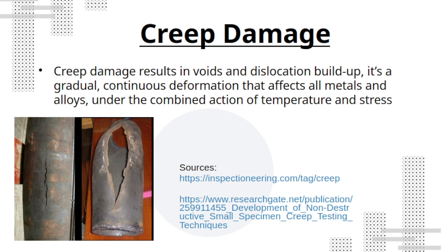Creep damage results in voids and dislocation buildup. It's a gradual, continuous deformation that affects all metals and alloys under the combined action of temperature and stress. And its main driving force is a constant high temperature and mechanical stress over time.